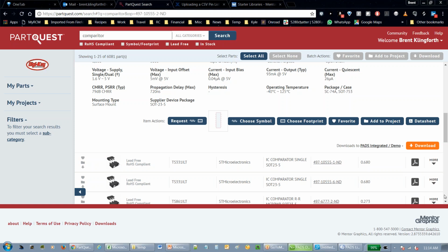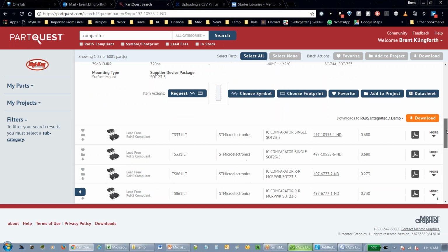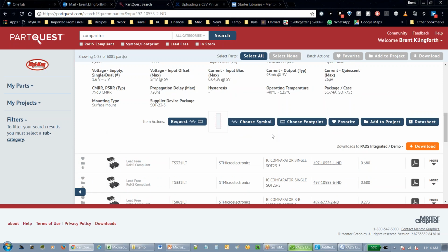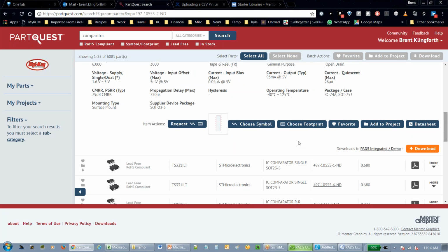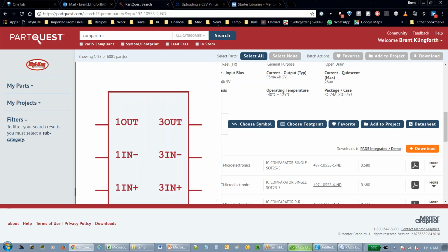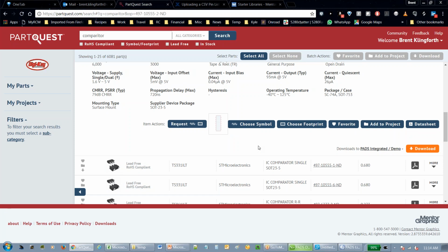Got another one post that is a very important feature of using Excel instead of trying to do all that stuff by hand. I've had people tell me they work an entire day on a 500 pin symbol for their schematic tool, when I've created a 1,000 pin part for some people, just as an example, in 10 minutes, copying stuff out of a data sheet and putting it in Excel, and then using wizards to create your part.